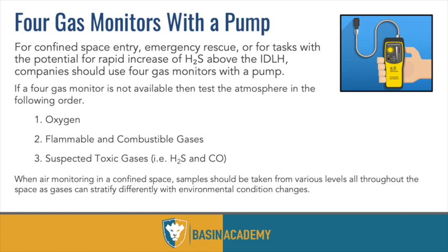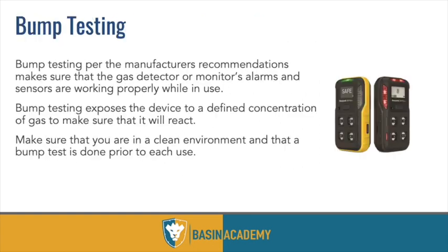So the pump is designed, you put it out there, you wait a few seconds from wherever you're reading, and it's going to bring you back a reading of where your measurement device is and what the levels of concentrations of, again, H2S, SO2, CO, whatever gases it is you're measuring, that's their designed purpose. So again, they need to be bump tested every day.